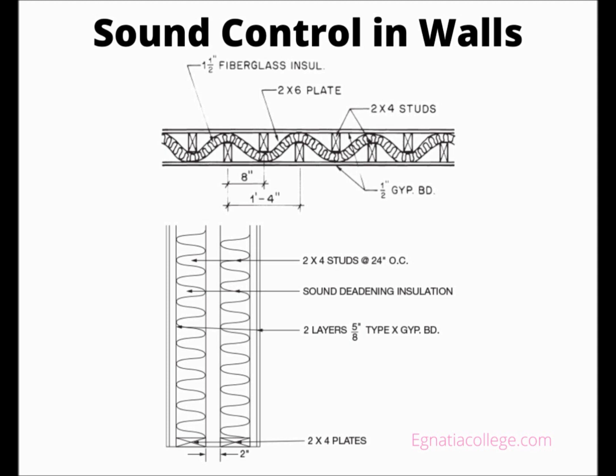The drywall joint between the wall and the ceiling may require sound deadening putty to prevent sound from passing through that joint. The electrical installer may be required to utilize acoustical insulation or some other sound attenuation material around flush device boxes. Raceways may require installations that reduce sound transmission, such as expansion joints, flexible raceway, or raceway offsetting through the party wall.